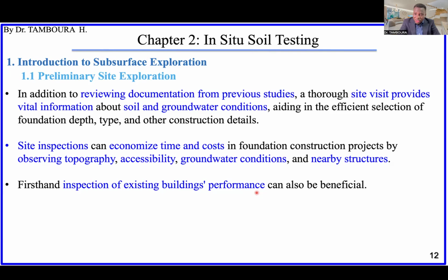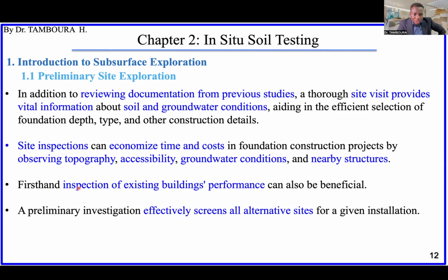So if you go and check the existing buildings, sometimes you can even get the subsurface exploration report of those nearby buildings, and it can help a lot. That point is very important.